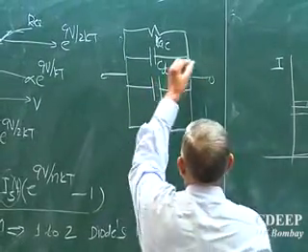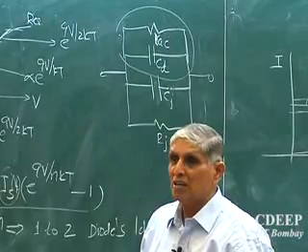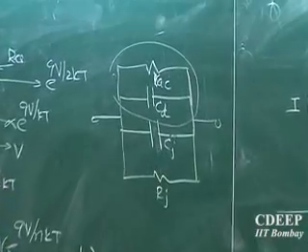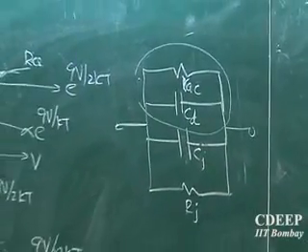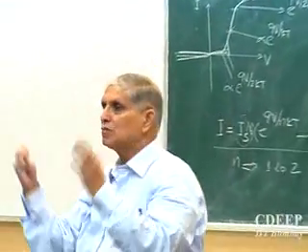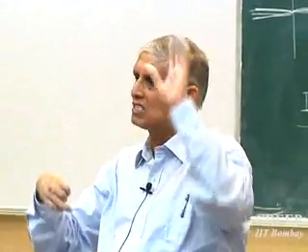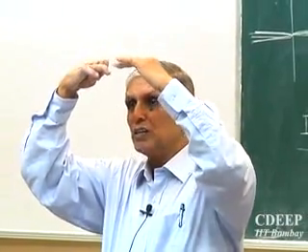However, in the forward bias, I just calculated R_AC, and I must evaluate this term C_D, which is called diffusion capacitance. Is that clear? Diffusion capacitance, in forward bias. What did we think in the reverse bias? Junction capacitance. Now in this case also there is a junction capacitance, because the depletion will reduce, so C_J will be still higher. Doesn't matter, because if it is higher, 1 upon omega C is lower, so that will not be very crucial for us. But this diffusion capacitance will be very crucial for us.